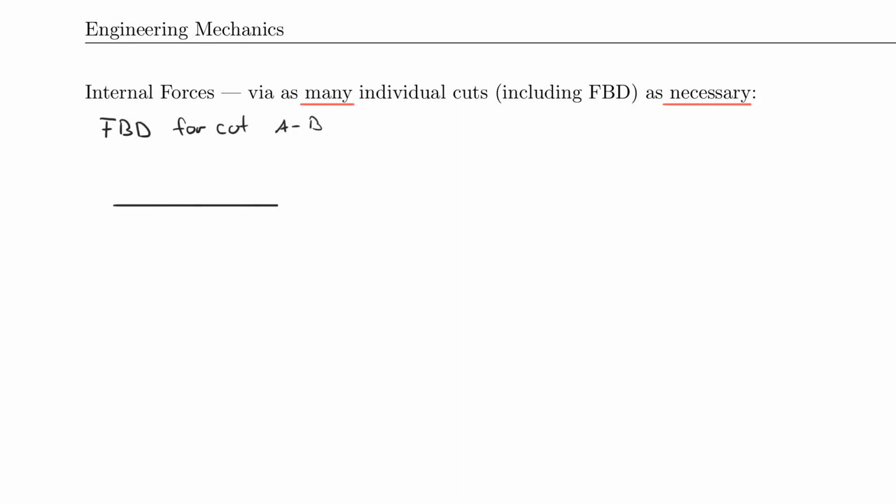So I have my free body diagram here, which how that works we really showed you in the previous lecture, but I cut it here at B, and I had support reactions which were 5 kilonewton pushing up here, and I had a 0 here, so I don't even worry about that. But then there was no other force on the system. Remember that? There was no force except that one.